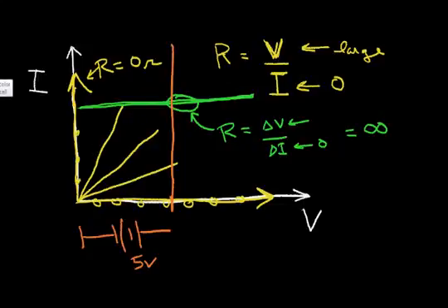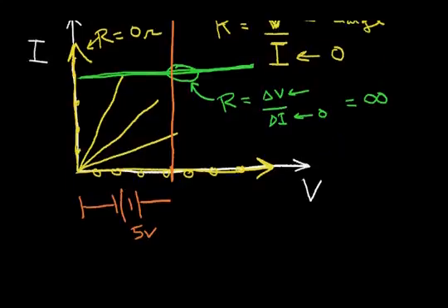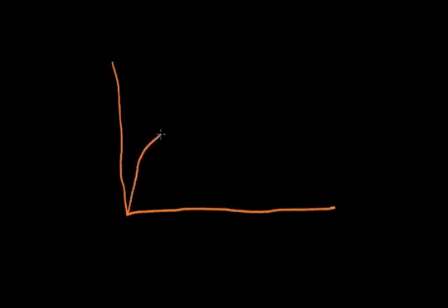So when I plot the MOSFET transistor, let me scroll down here. I plot current versus voltage. There's a resistor region. Then the resistance increases and it becomes almost a current source, which is infinite resistance, then eventually it breaks down. So let's first relate this resistance region of the curve to what's going on inside the channel of the N-channel MOSFET transistor.